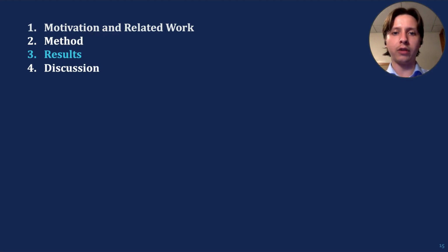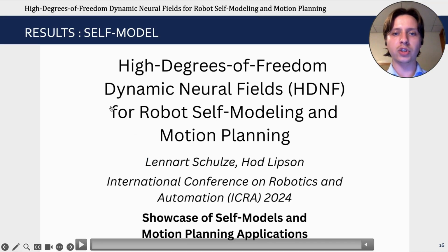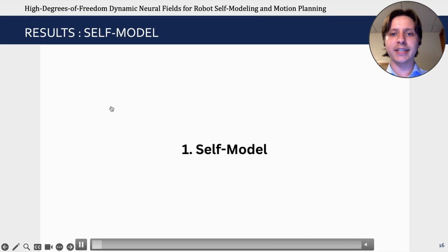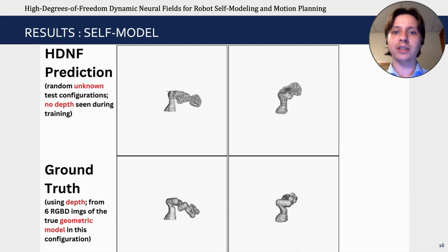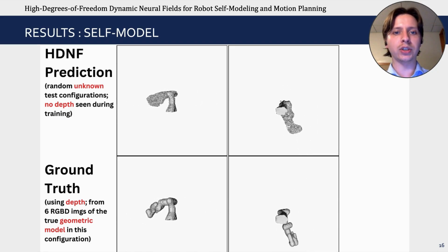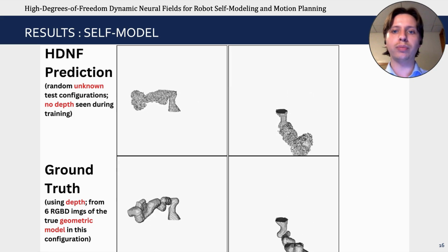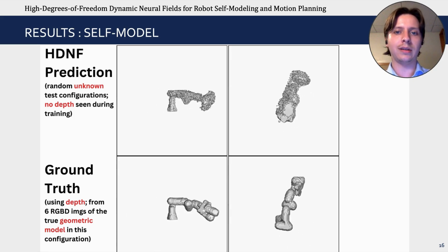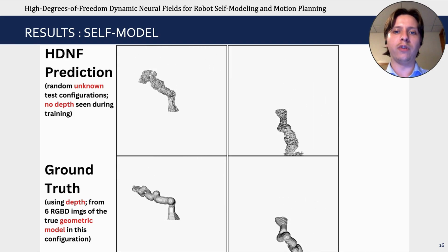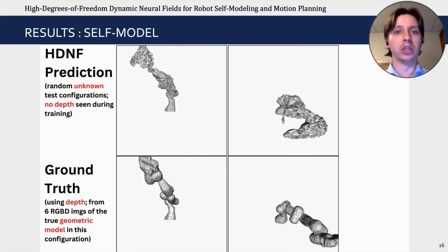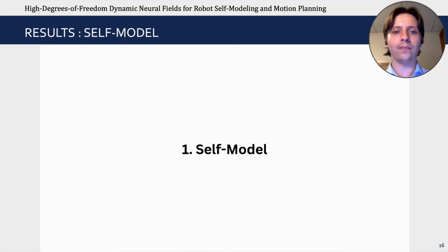We initially verify our results regarding the general capabilities of the learned neural field in 3D reconstruction. We successfully conditioned the robot's shape in space on its joint configuration, which allows us to query it in unseen configurations with an average chamfer distance of 2% of the workspace dimension. We can also change the view of those reconstructions. However, the volumetric rendering incentivizes a non-smooth surface.